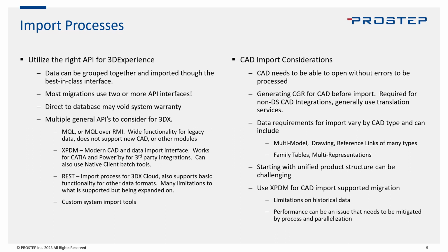There are a lot of data requirements that you need to resolve and provide to the XPDM interface when you're doing this through the import. So all those relationships, like the multi-models, the drawing links, the family tables and other types of internal relationships, you have to evaluate the CAD data, scan it, and make sure you know all the dependencies of this CAD data. Then provide that through XPDM so that at import time, it knows exactly what to create.